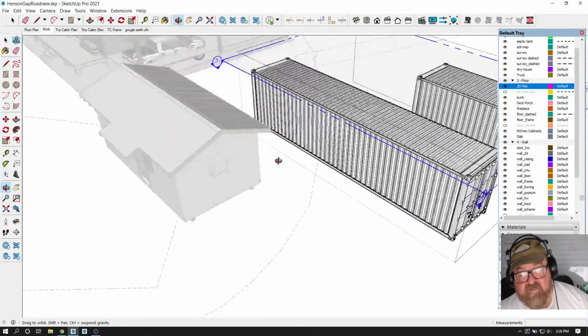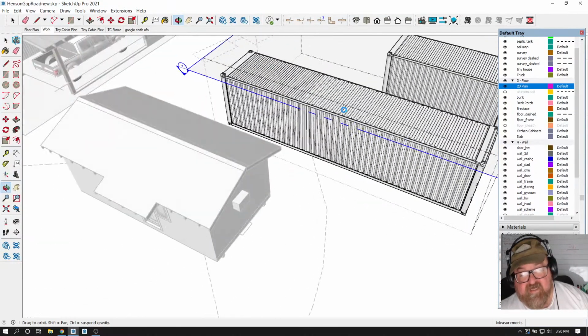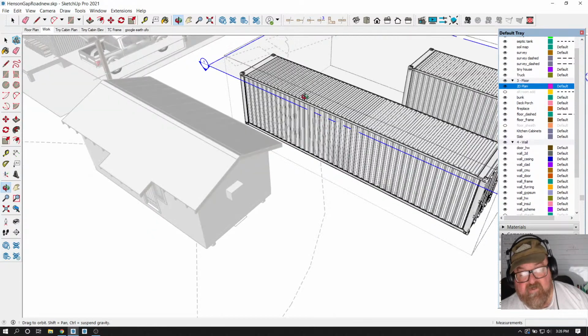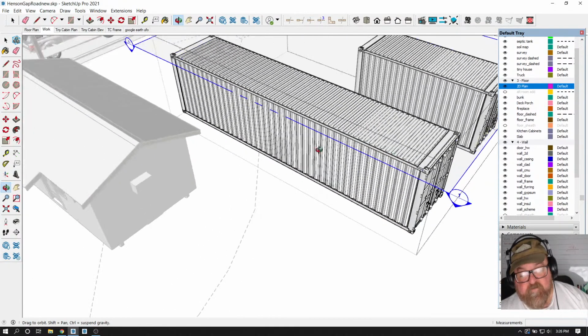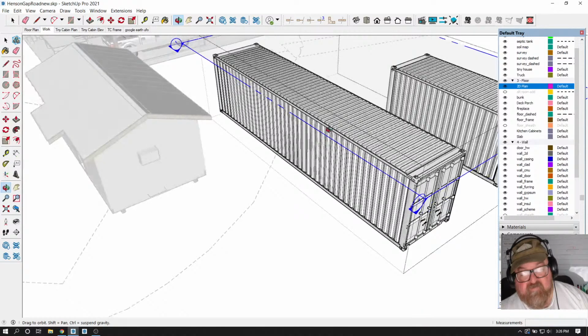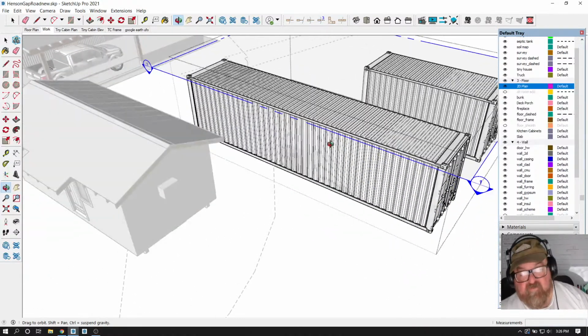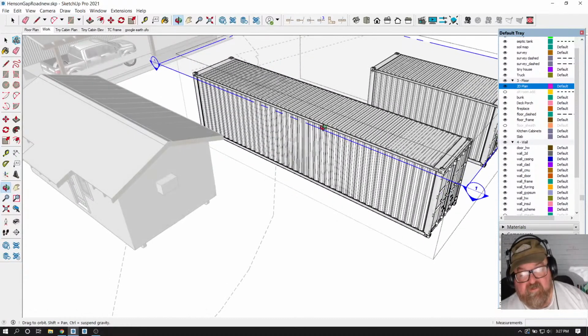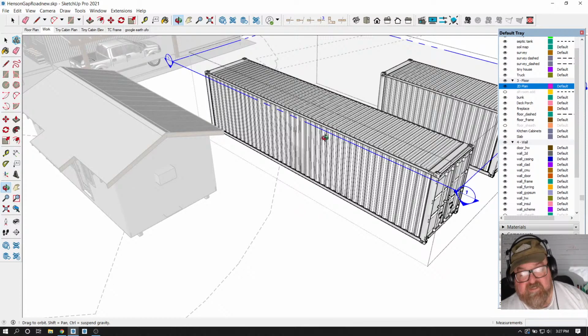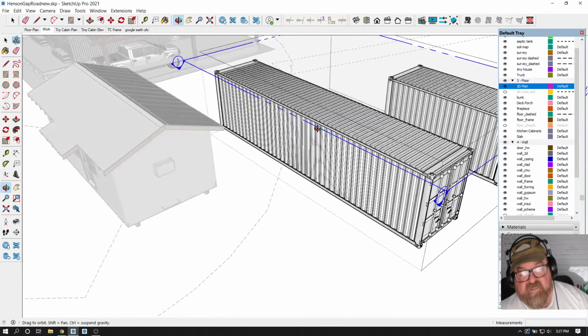The other thing you're going to have to do is frame out the inside to put insulation in there. If you try to live in this without insulation, you're going to be living in a tropical rainforest. Literally, depending on where you are, in the summer or the winter, if you try to heat and cool this thing from the inside and you don't have insulation, you're going to have sweat.